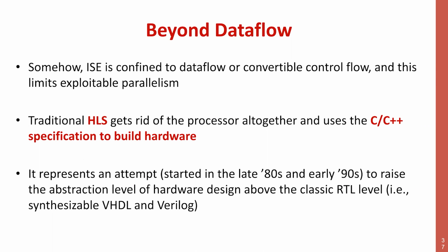High-level synthesis is this idea of creating circuits from a software or programming specification. And let's assume that for the rest of the day and the course, that this is C, C++. So the idea is to replace essentially what Verilog and VHDL represent. They are RTL, register transfer level languages, where essentially you place down registers and place clouds of combinational logic in between them. And you do this almost explicitly, right?